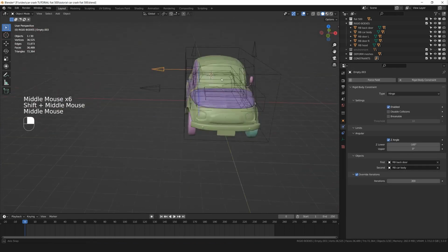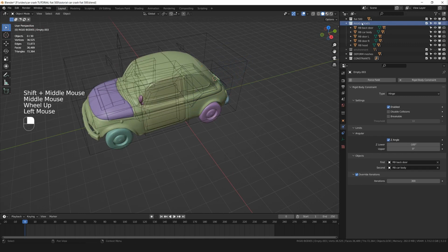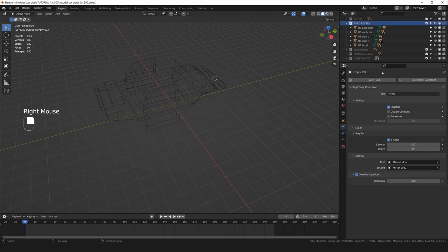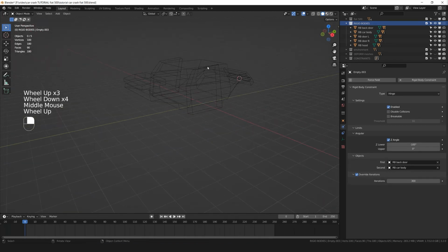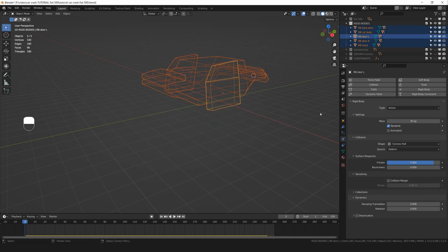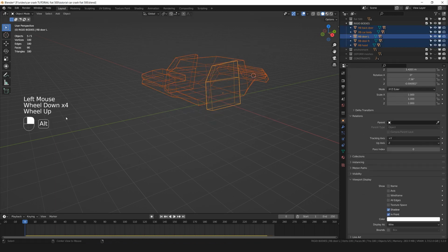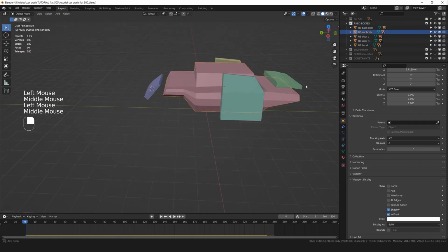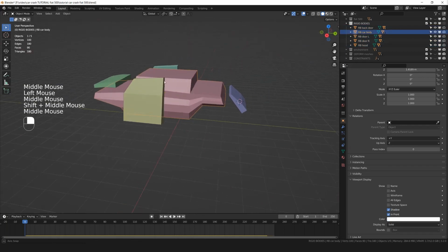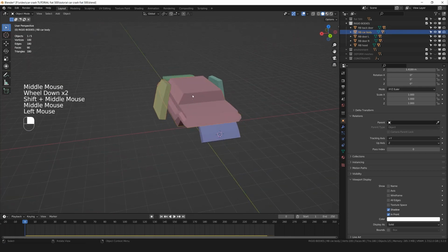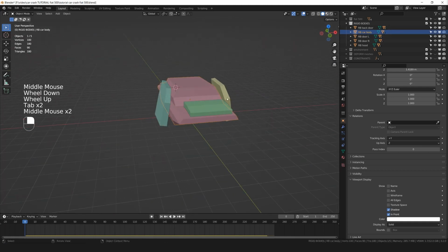And now I want you to pay attention to this thing. Select the rigid body collection and right click and click on visibility, isolate. Now we are looking only at the rigid bodies that compose this car. Let's select one of them and then all the others. Then let's see them better. Let's go here and holding Alt, I'm gonna click on Display As, Solid. Alright, these are the rigid bodies. So this ugly thing is what is driving the physics simulation with collision and stuff. As you can see, they are more or less cubes with a very low poly count. Just a couple of faces extruded.